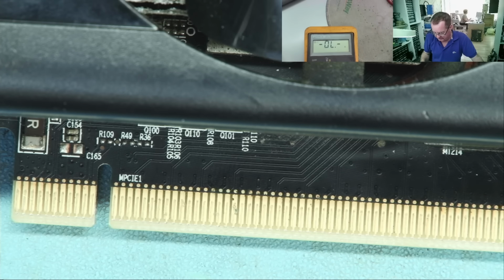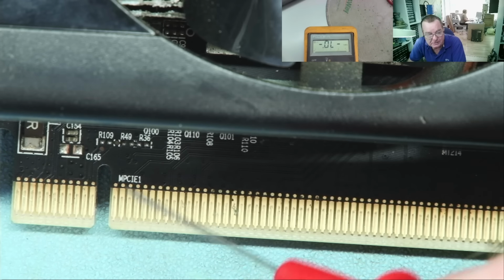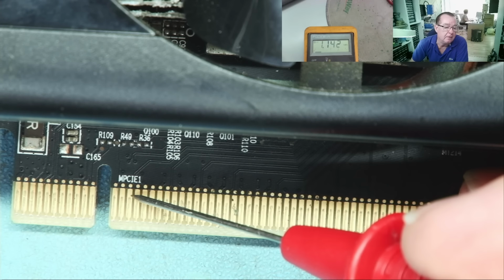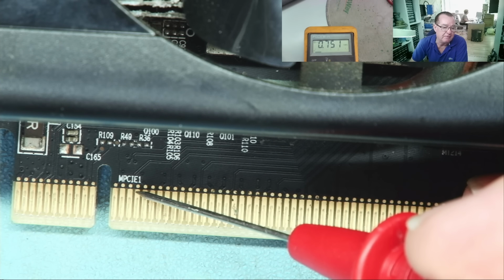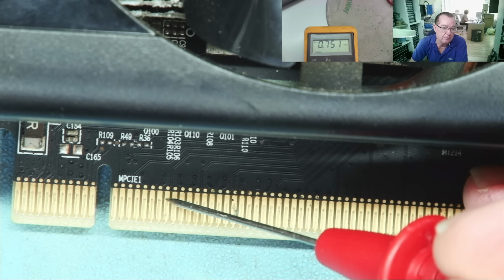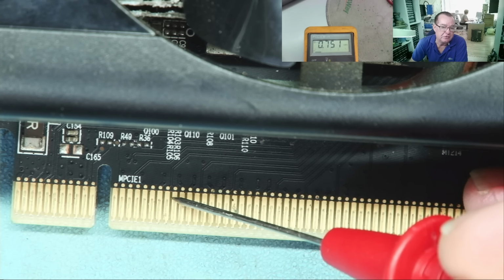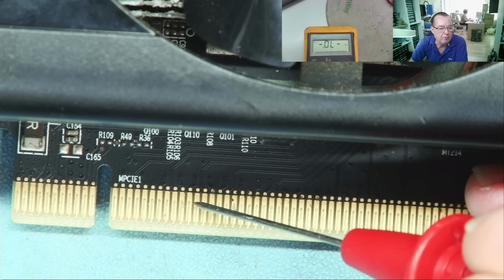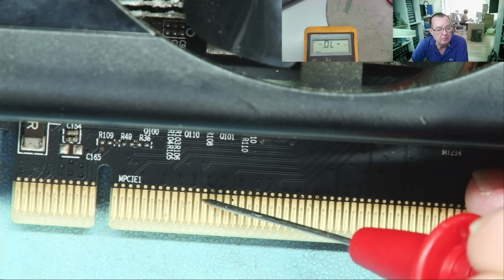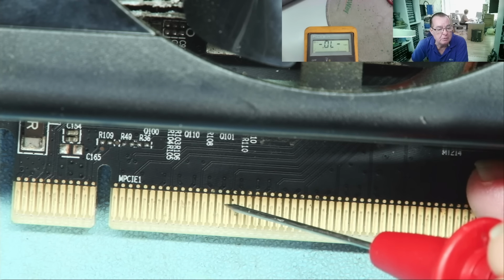We'll put the meter into diode mode, okay, and let's check. So we can see the first lane, it comes down here and it reads 0.751. So those two read the same as each other, and these should all read 0.751. Now, I'm not saying they might not read 0.752 or something very close, yeah, or 0.749, but there shouldn't be any great difference. So that one's 750, that's okay.